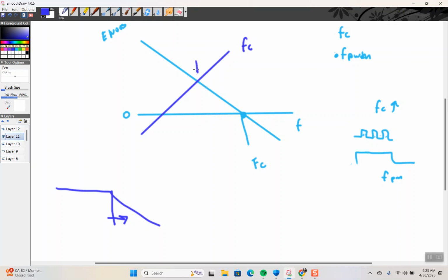And so you end up taking the geometric mean, and right here in the middle is like F max, and this would be the effective number of bits. So this is all in the lab manual, and I think it's better to do than to hear me talk about it, right? But it is this trade-off. And what's nice though is this region is very flat. So changes in clock frequency don't affect the number of bits that much.